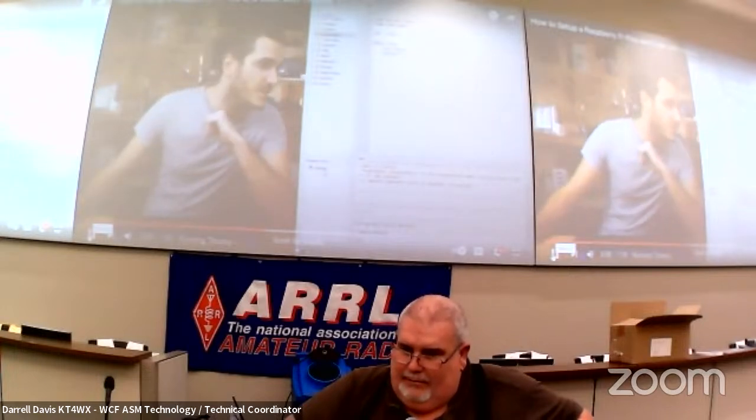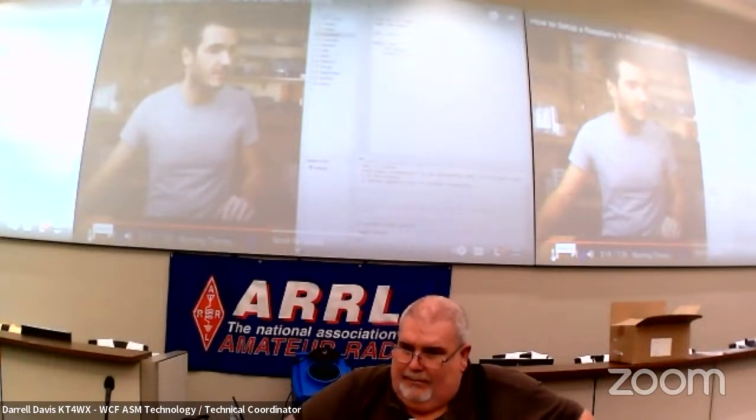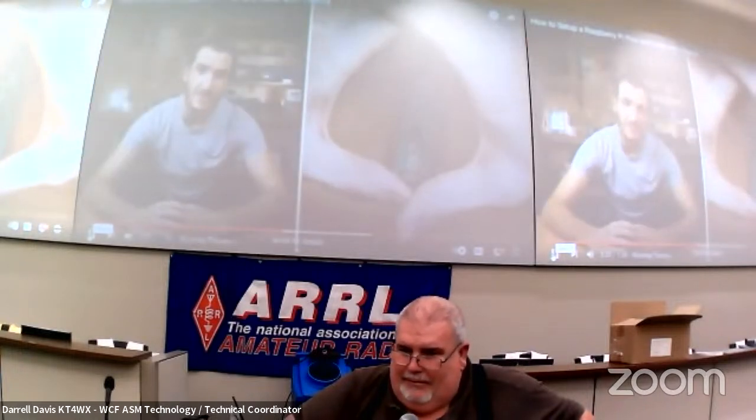If all goes well, you should see on your Raspberry Pi Pico there is a new file called main.py. The file isn't actually executed yet. For that, we need to restart the Pico. From that REPL interface, you can press Control-D. That's called a soft reboot command. And now that the Pico has booted up, it's going to look for that main.py file and run it. See the LED on the board blinking?